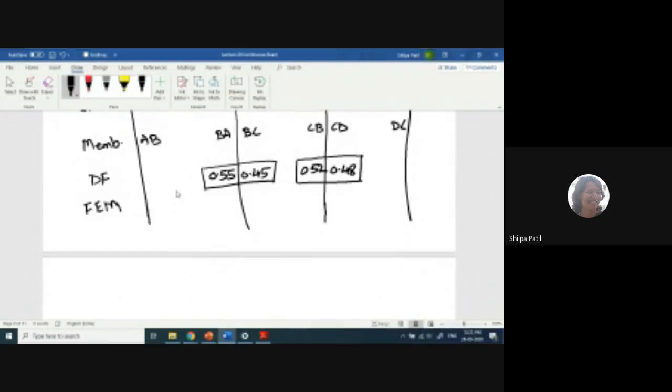So tell me now the fixed end moments. For AB, it is minus 17.25. For BA, it is plus 17.25. For BC, minus 35.42, and for CB, this is plus 35.42. For CD, minus 33.33, and DC, it is 33.33 again, but positive.